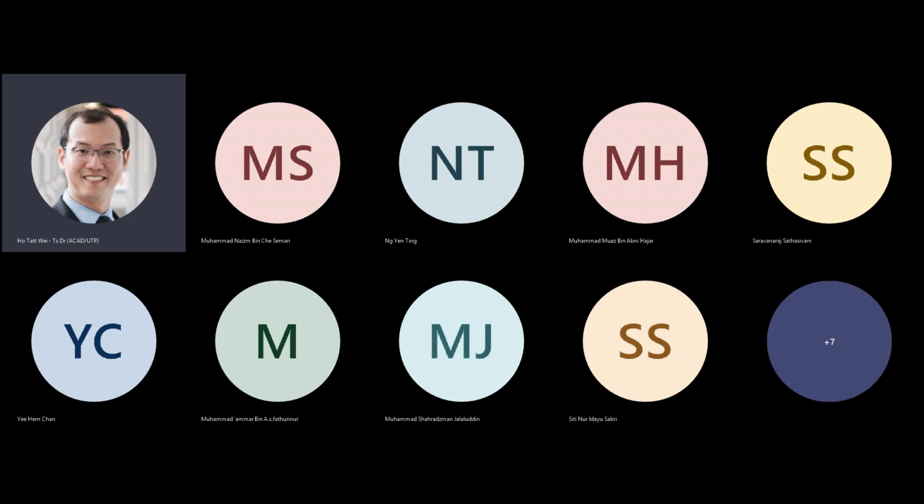And this will be the same for the NOR gate. And so the first competency, the first skill you would need to develop is to be able to see quite quickly, to be able to memorize and remember, how do you assemble this basic NOT gate, NAND gate, NOR gate out of complementary MOSFETs this way. And we approximate the MOSFETs, in the first instance, by a switch.